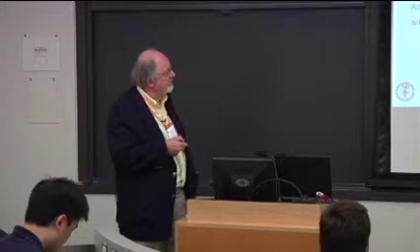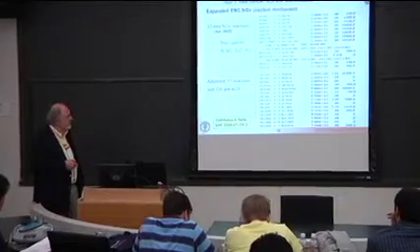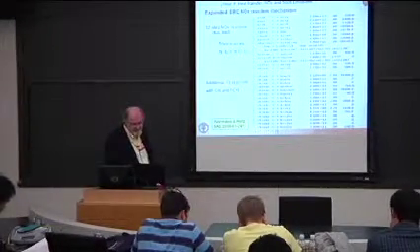So we started out with our simple reduced mechanism from the GRI mechanism with 12 steps for NOx with these 4 species. But now we're going to add additional species and more reactions to account for cases where you are on the rich side of stoichiometric.